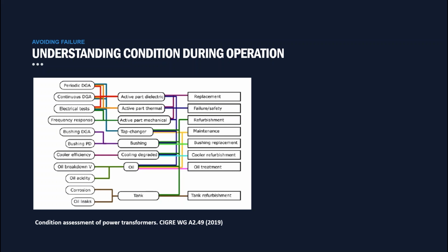And we can evaluate the involvement of paper in a heating fault if we see elevated levels of carbon monoxide and carbon dioxide in the dissolved gas analysis, although this assumes that large amounts of paper are involved, which may not be the case if the fault is, for instance, in a paper-covered lead. We can also apply dissolved gas analysis to tap changers to help us identify problems that can be managed with an appropriate maintenance response.